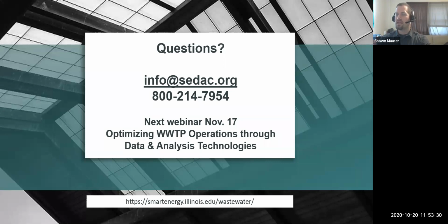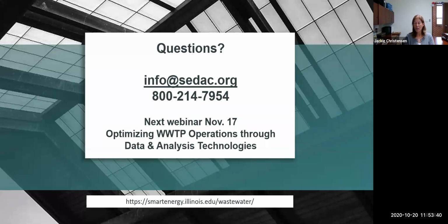Mary Dressel, Jackie, I think this might be for you. Asks, how often do you run total phosphorus testing? The operators do a grab sample every day, and they're out there 5 days a week. For permit testing, it's 2 days a week. Okay, thank you.